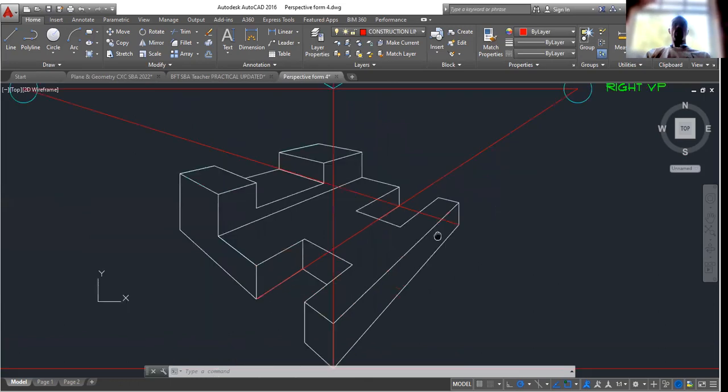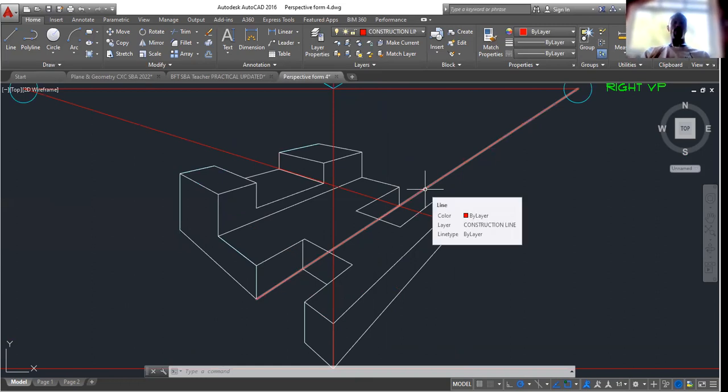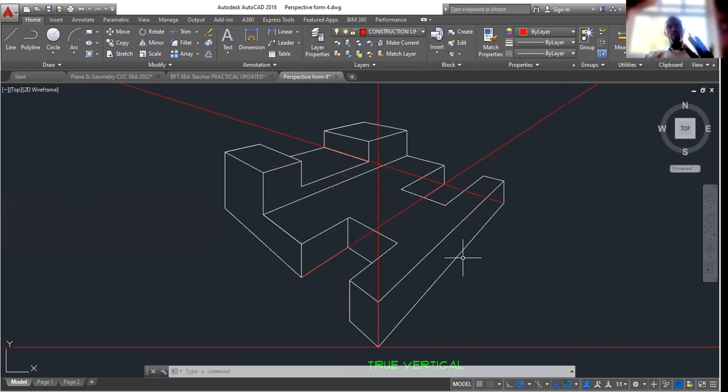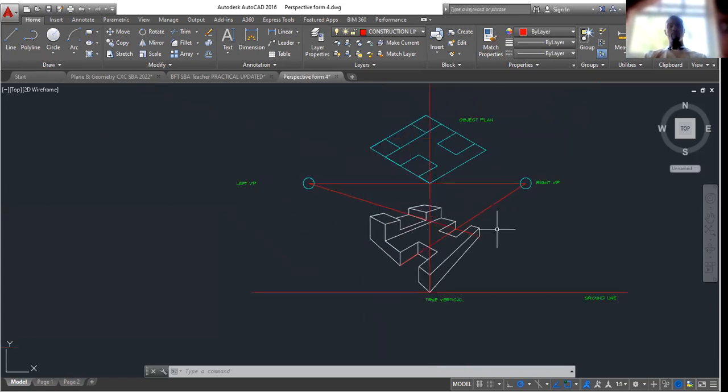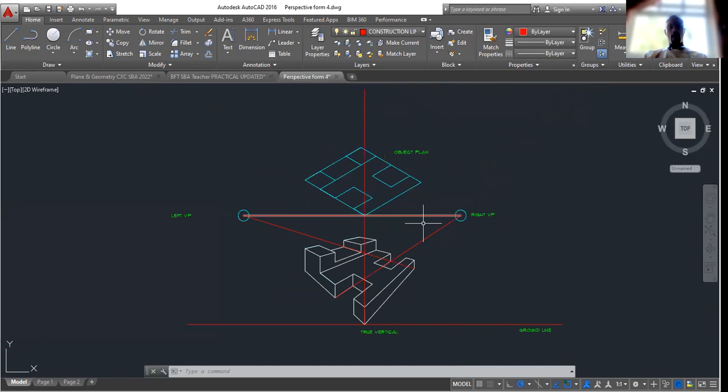So the horizontal lines do not change. All right, everything that comes on the same straight line, it will appear the same even on a perspective drawing, because in examples that we looked at where you are standing at the edge or the beginning of a highway or a stretch of road, all the bottoms of the poles end up on the same straight line, all the tops of the poles end up on the same straight line. So it doesn't make this drawing any different. All right. So let's go ahead and do our initial setup.